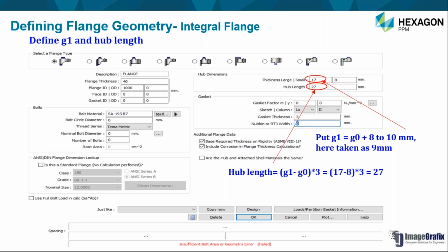Another criterion is the butt welding angle of 70 degrees, which should also be met. Also, if any repair comes, we have to address that repair, and the access in that 12 mm will be very minimal. So it is difficult to address all these things.